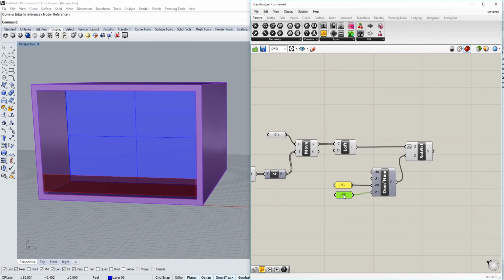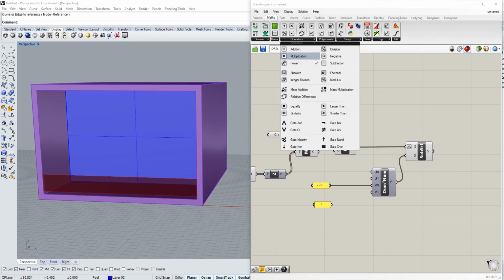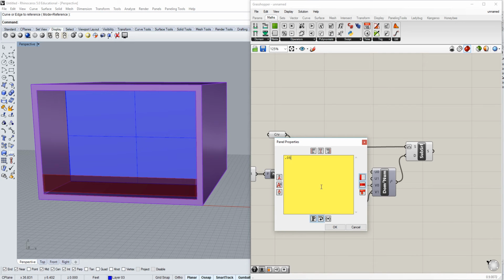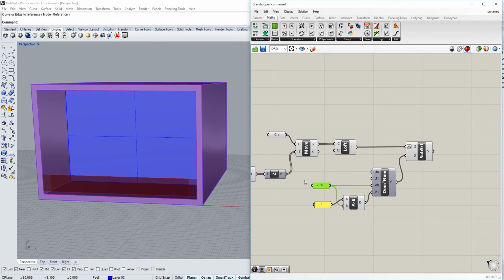Okay, sounds good. Also, if you wanted to make it really fully parametric and you wanted it to absolutely be even on both sides no matter what, you could get rid of this and use 0.01, but then for the other one, you start at a value of 1 and then you subtract the 0.01, and you put it in under math, operators, and subtraction. So you say 1 subtracted 0.01, you put it here. So that way if I change this even to 0.05 again, then it's going to reduce both sides. But I'll leave it at 0.01.